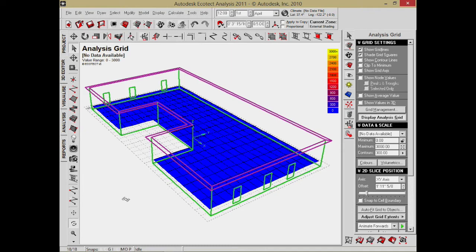Okay, you got a grid in a small space, right? No worries. Go back to this thing that says auto fit the grid. It's this guy right there. And then let's say within, and then just say okay again. There we go. It manually placed one in just a small square, and now you want to get the whole boundary. Beauty. Okay, over here looks like we need a little help auto fitting our grid too.